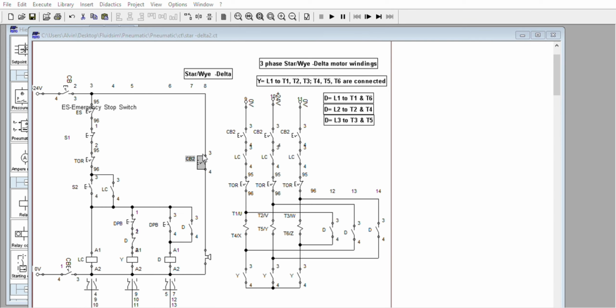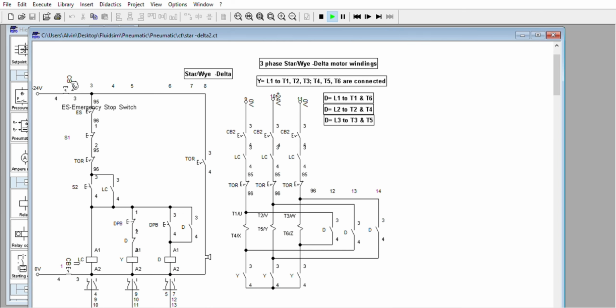So this is TOR. You can write OL, overload relay. That's fine as long as that is not a red notification. CB is not turned on. Turn up, simulate this one, simulate this one. Okay, so you cannot turn on because that is open. Alarm. Turn off the circuit breaker, do not reset the overload relay. Find the trouble. This one, that's fine.